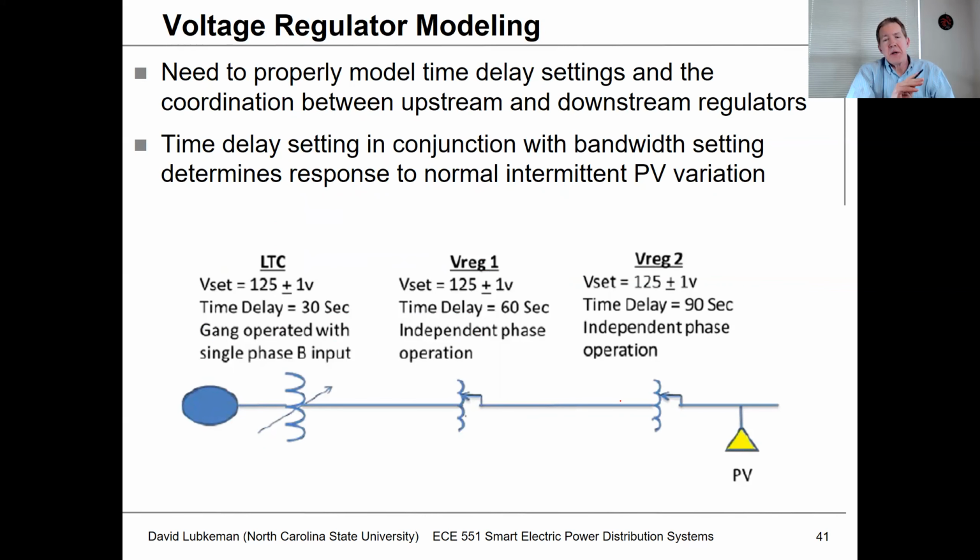One thing I want to mention here is that voltage regulator modeling is really key. And we talked about this in class as far as a set point and the bandwidth. And we also talked a little bit about what should happen if we have reverse power flow. But one thing I didn't mention is how we coordinate line voltage regulators. And the way we coordinate voltage regulation is through what's called time delay.